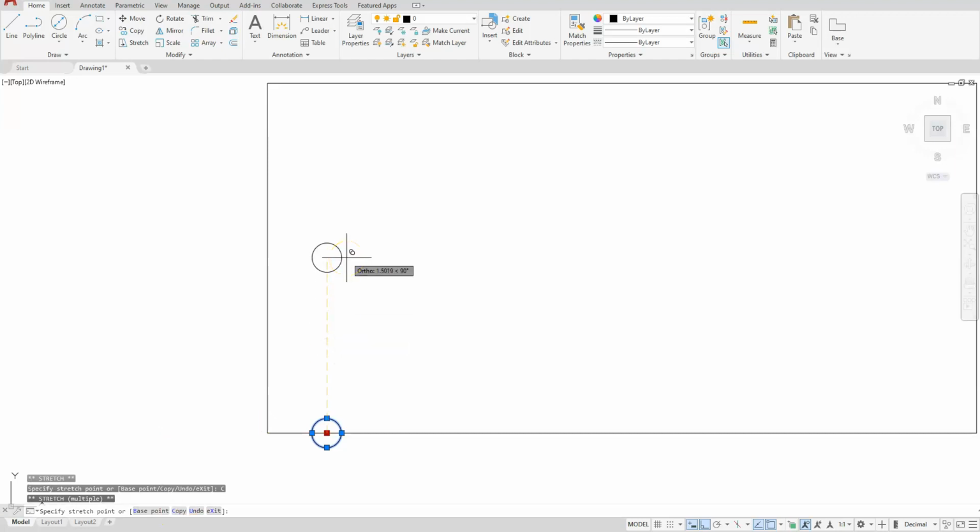And now I'll type in the numbers that I need to reference where these circles are. So my first circle is located at 0.25, and I'm just hitting the enter button after it. My next one is at 1.125. Next circle should be at 1.875. And then my final A circle will be at 2.75.